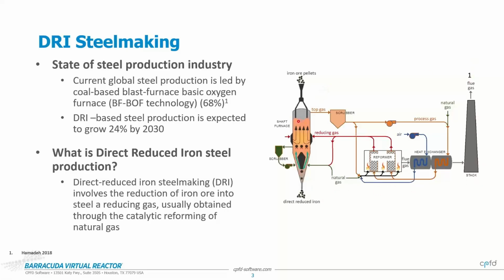So those solids, as they undergo reduction, travel through this moving bed. They're transported down here into what is called the cooling zone. In that cooling zone, they interact with a gas rich in methane that is fed in here, where they continue to travel and they're extracted here from the bottom as the final product.